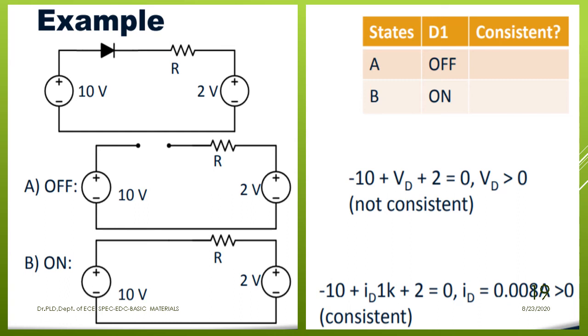If the anode voltage is greater than the cathode voltage, the diode becomes forward biased. If the diode becomes forward biased, we consider it a short circuit. If it is a short circuit, the drop across the diode is, ideally speaking, 0. Practically speaking, at the maximum, 0.7 volts is the drop across the diode in its forward bias. Whatever the voltage may be, it equals the current flowing through the resistor times the resistance, and the current flowing through the diode times the resistance offered by the diode.